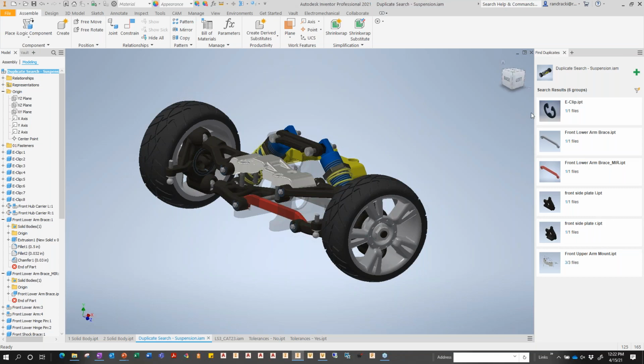And in the assembly, we found a potential of 6 different files that could be duplicates on the system. What the browser is showing me is there's one other duplicate that it's seen besides this one. If I come down below here, we highlight the parts on the screen. As I move my cursor up and down, just like in the assembly browser or the feature browser, we're highlighting geometry on the screen. So it's easy to locate the geometry.